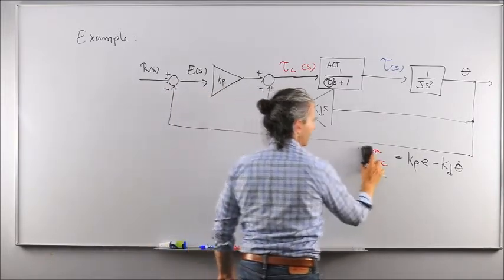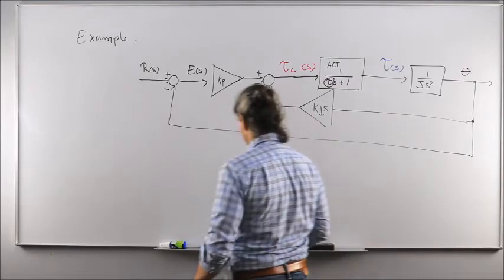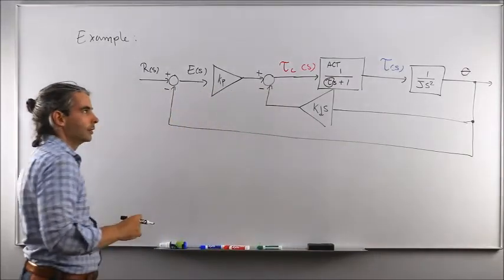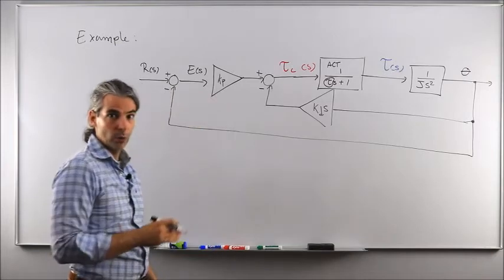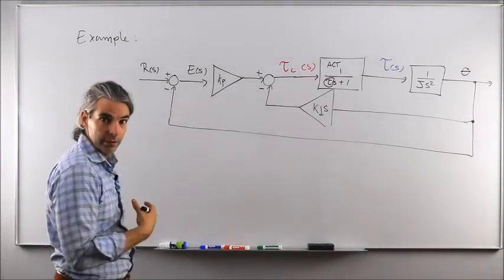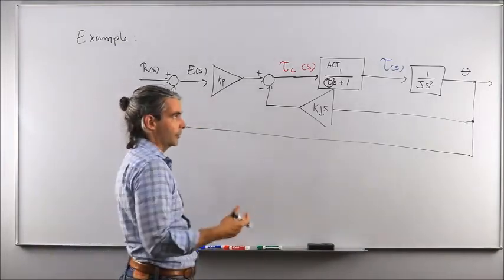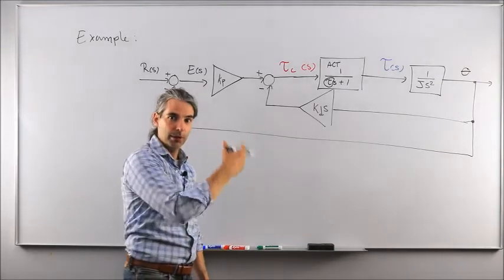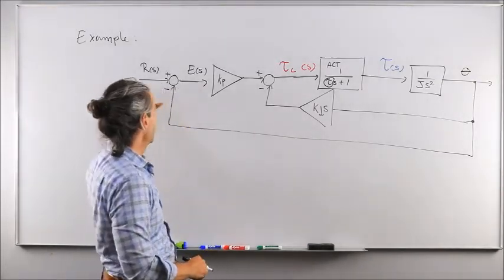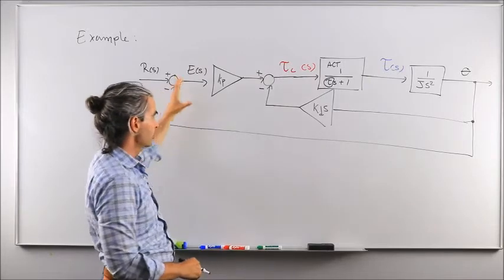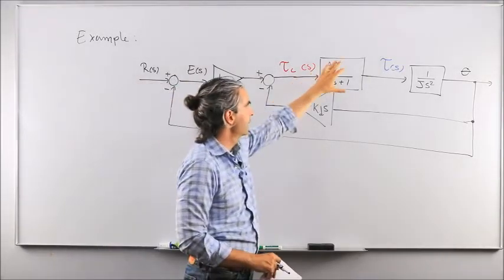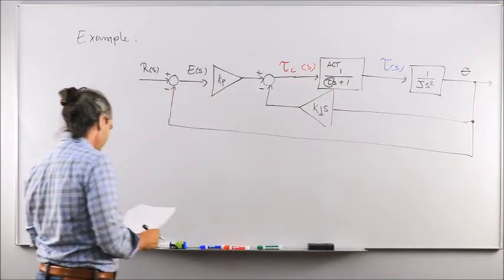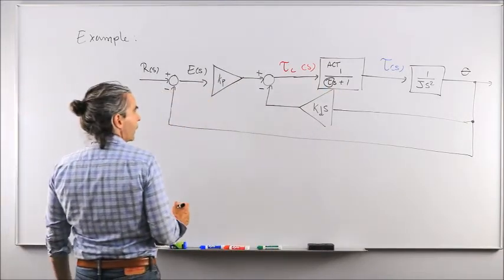So, how can we apply Routh stability criteria in a practical application? Closed loop transfer function. Closed loop transfer function always with Routh, okay? And in our context, this is not some random math we're doing. This is engineering, and spacecraft engineering. So we want to know if the whole system, as a closed loop system, will remain stable or not by adding this block in between. Okay.